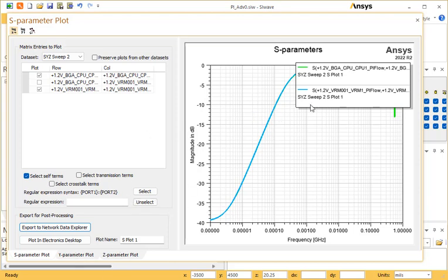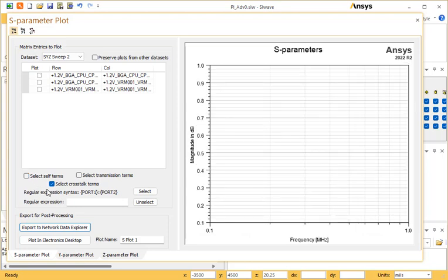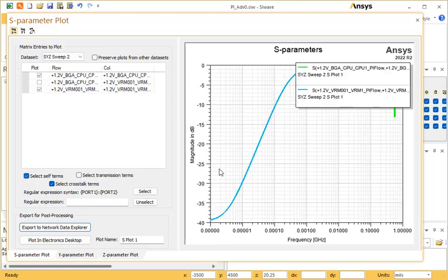If we cannot tell, then we cannot use them, especially if you are looking at crosstalk with so many lines. You have to make sure that the return loss of your power planes is extremely good, like -40, -50 across the band of interest, to make sure that the crosstalk results are reliable.